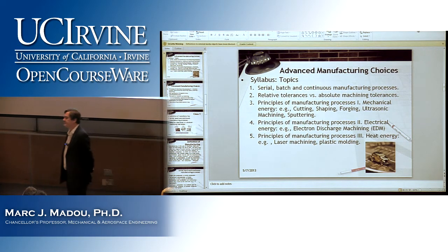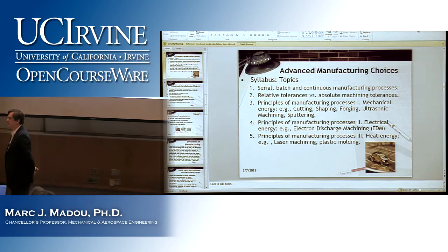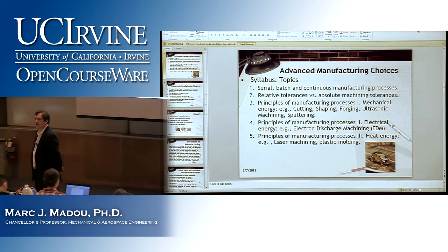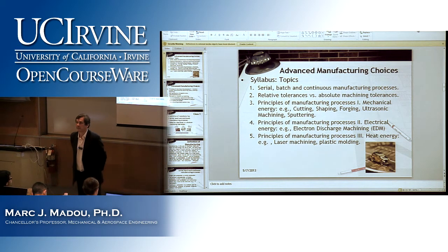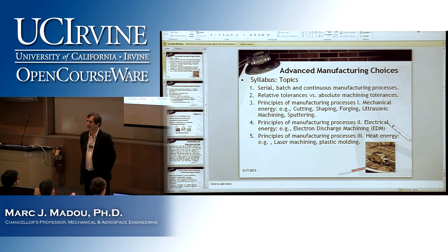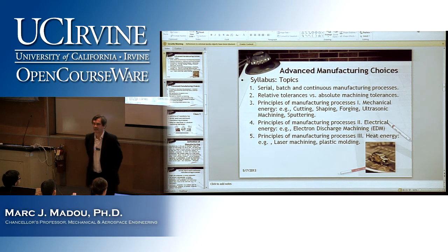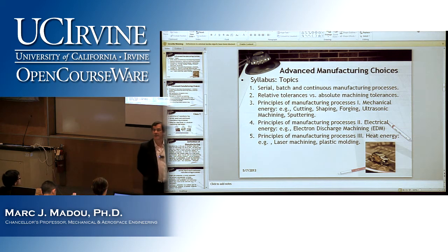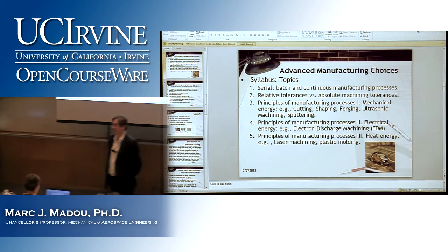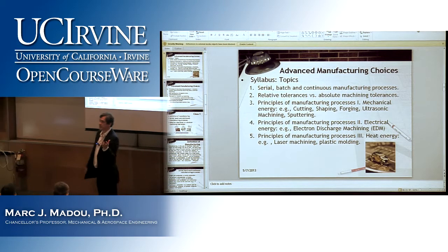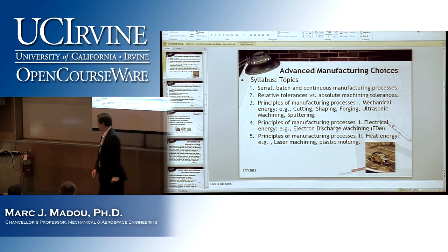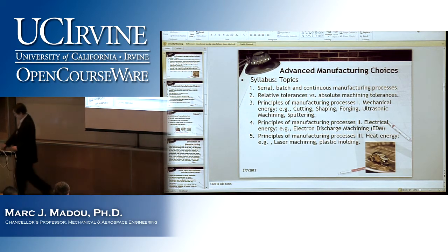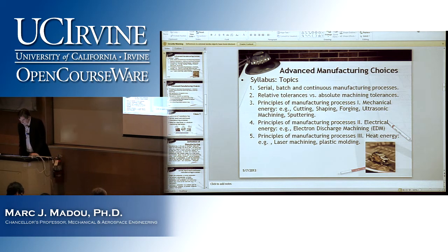So for example, nanomachining, will the relative tolerance there be better than, let's say, traditional mechanical machining of a lens? It will not, right? So make sure you understand that and remember that very point. The difference between absolute tolerance and relative tolerance. Get that understood.